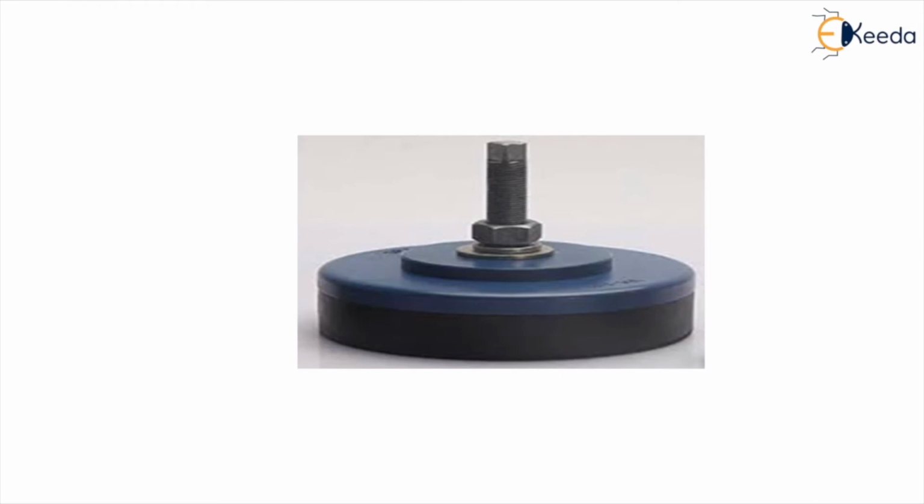Now, we have already discussed that these mounts comprise two components, the rubber and the metal component. The rubbers that are used may vary depending upon the requirement. Natural rubbers can be used, which have high elasticity and high tear strength, and are quite strong materials with the best resistance to mechanical and dynamic loads. But again, they have certain disadvantages. They are not stable, especially with non-polar liquids. So some additives can be used to make them more efficient, right?